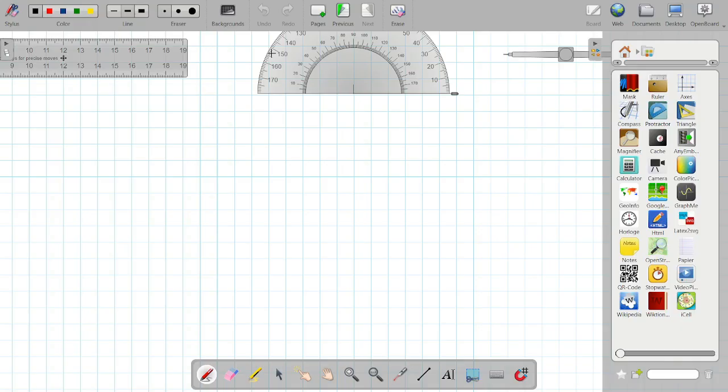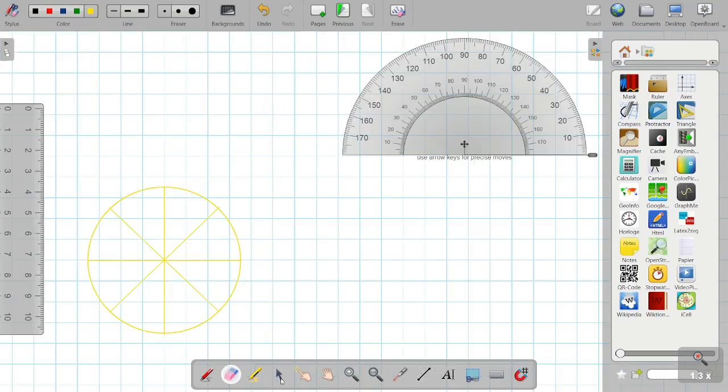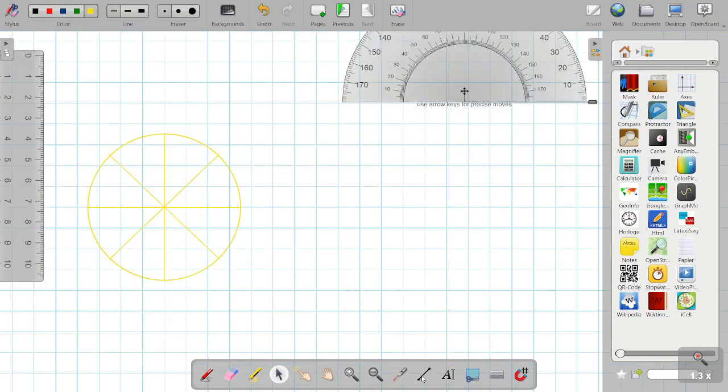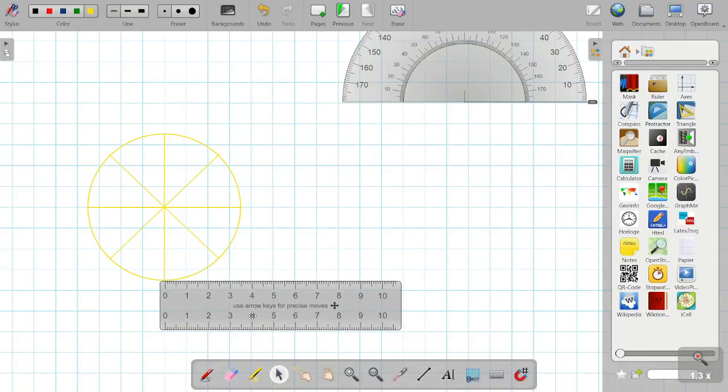So first we will make a circle of radius 35 mm. Now, after drawing the circle and dividing into 8 equal parts, now we have to draw a line which is equal to the perimeter of the circle. So as this is a circle of 70 mm diameter, that is 35 mm radius, if I calculate the value of perimeter, that is 2 pi r, it comes out to be 219.8. So we need to draw a line of 219.8 mm.